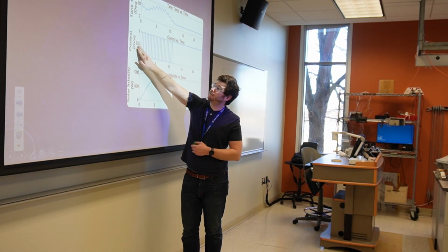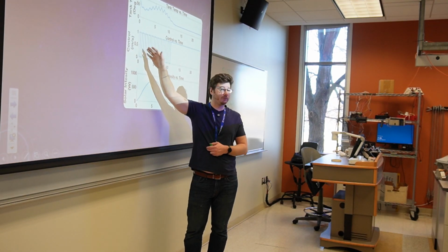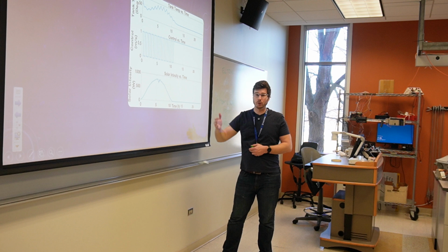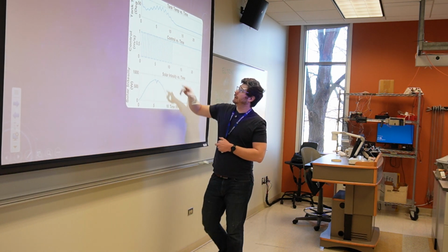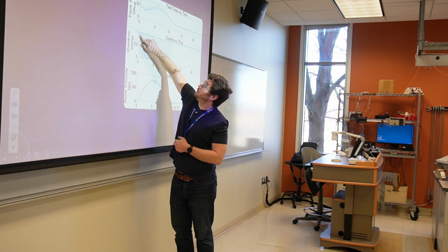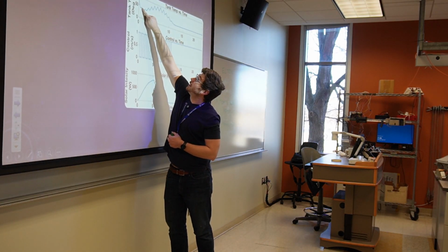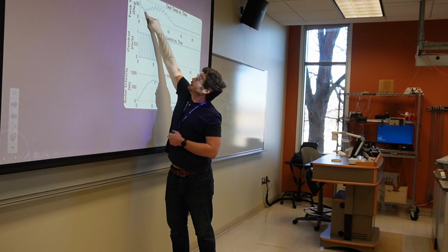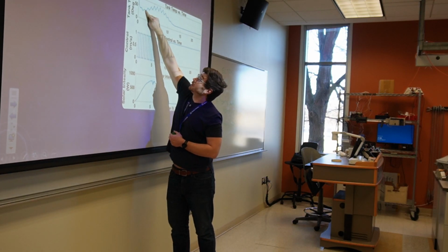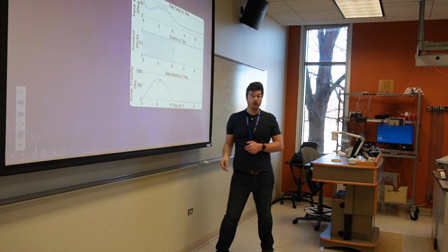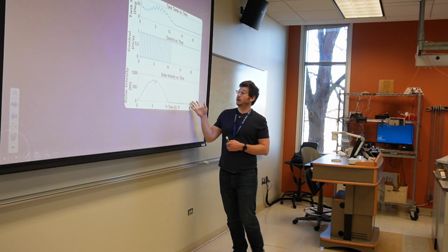If we were to turn it half on, you would see it go up to the 0.5 mark, but I guess it's not a variable heater, right? It's just on or off. And this is how the temperature responds accordingly. So you can see shortly after we turn the heater on, we get a little spike in our process, right? We turn it off, it cools a little bit, we turn it back on, it starts to heat up, and so on. And we might have other disturbances in that system as well.